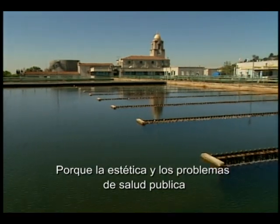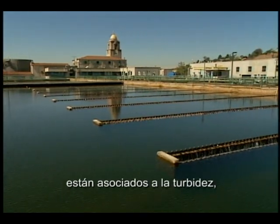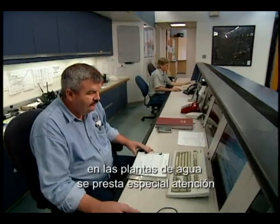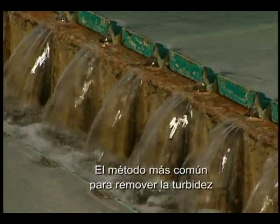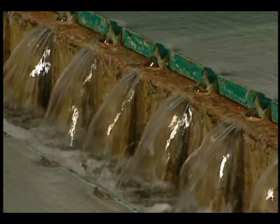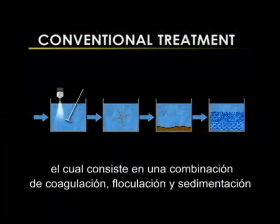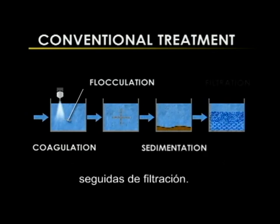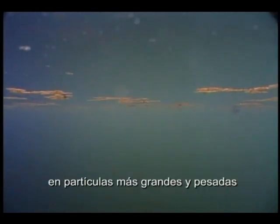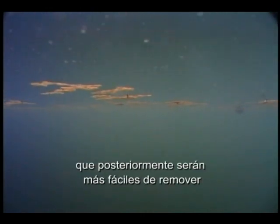Because of the aesthetic and public health problems associated with turbidity, water utilities pay close attention to turbidity levels in finished water. The most common method of removing turbidity is called conventional treatment, which is a combination of coagulation, flocculation, and sedimentation followed by filtration. Coagulation and flocculation agglomerate turbidity into larger, heavier particles that can then be more easily removed by sedimentation and filtration.